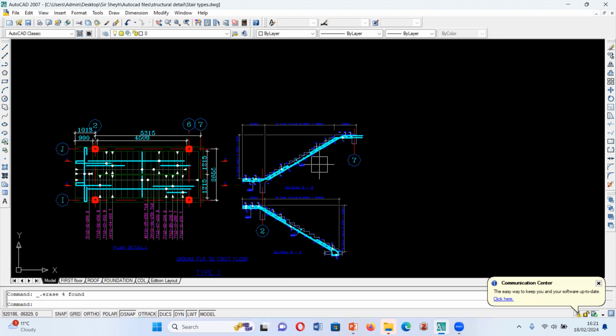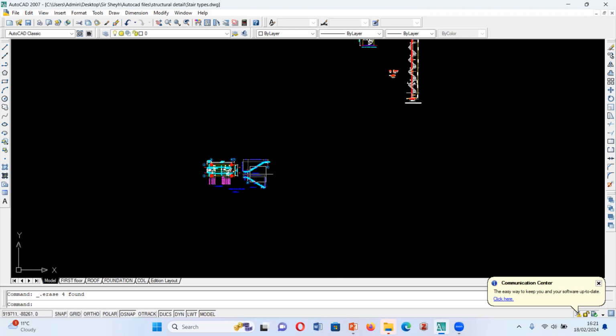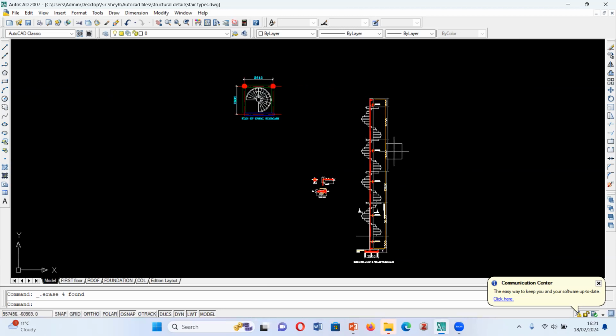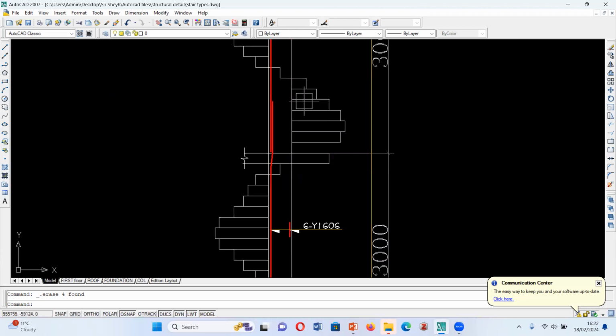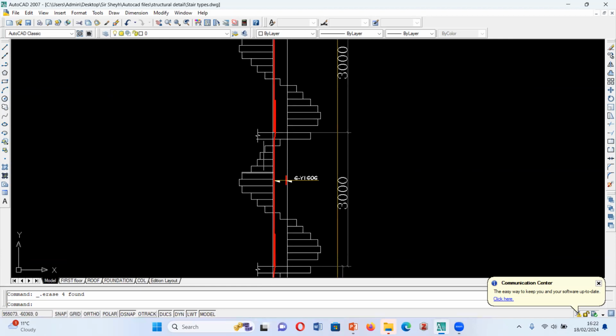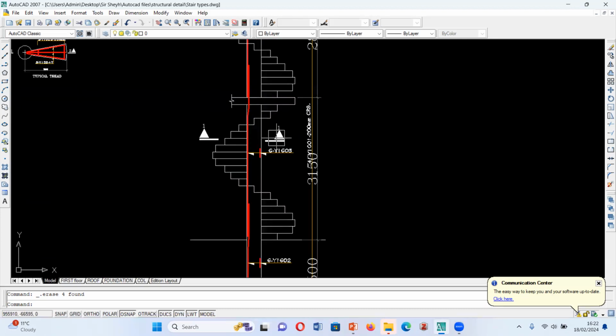So that is that about this type of stair, talking about the straight flight, the 180-degree half turn or quarter turn stairs. So I'm now going to move to the spiral stair. Talking about the central column, you're going to be having a central column, and then a series of steps that cantilever out from a circular column. Can you see? This is the foundation. This is the series of steps that cantilever out, and this is your circular column.